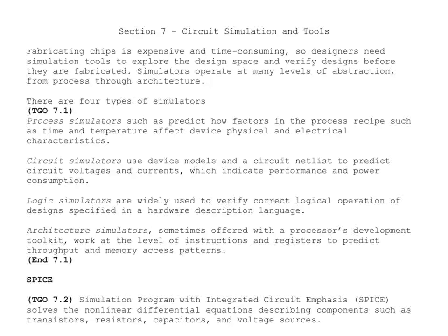Process simulators predict how factors such as process variations, time, temperature, and voltage affect all the physical and electrical characteristics. We're going to be looking at an example of something called a process file that actually defines the process, all the lower level quantum aspects of it, all the way up to your initial threshold voltage, your gamma, your electron mobilities for PMOS and NMOS, and how you can use that to actually simulate a circuit.